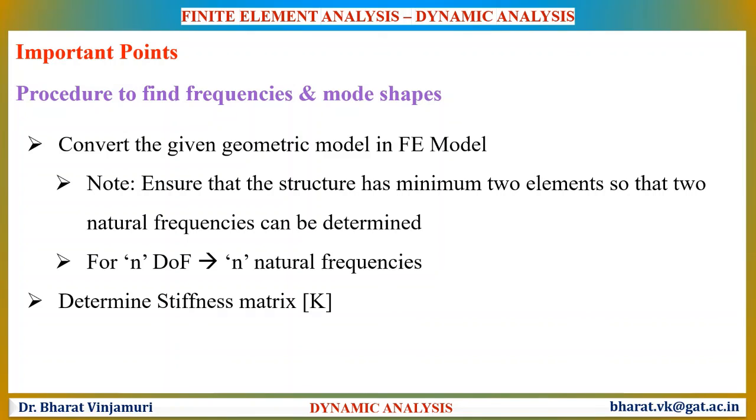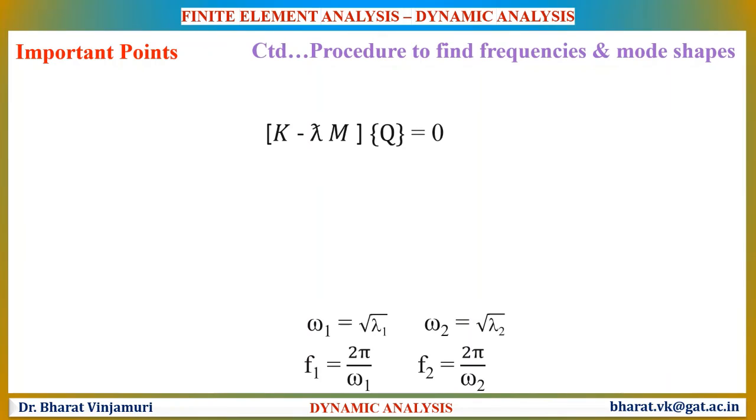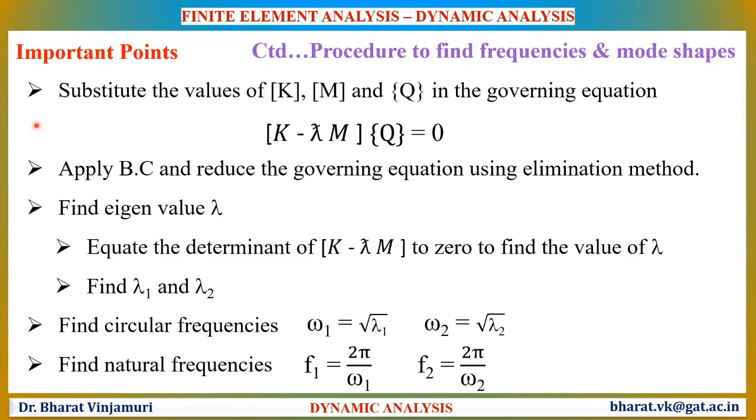In the next stage, after converting to the finite element model, let us determine the stiffness matrix as well as the consistent mass matrices by using the previous equations. Substituting the values of k, m and q in the governing equation will end up in finding the value of the eigenvalue. To obtain the eigenvalue, let us now apply the boundary conditions